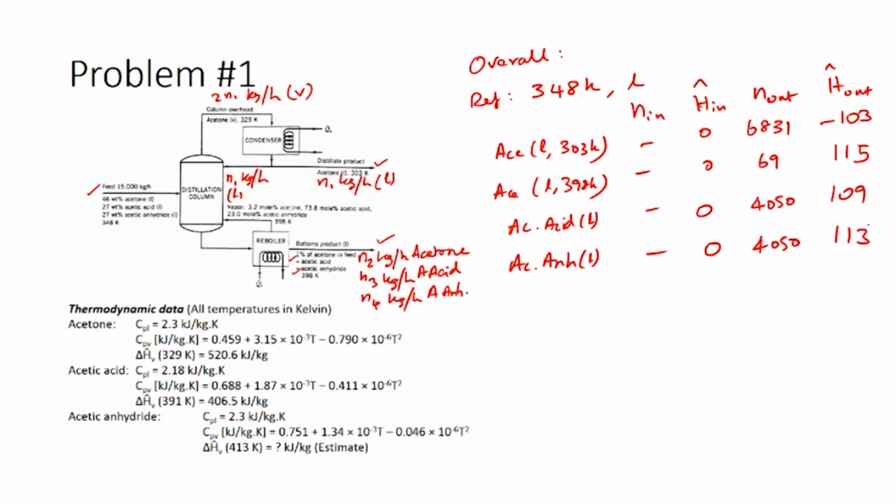So, now we can calculate the total change in enthalpy using this, and we would have to plug it into the general energy balance, the overall energy balance equation, to get QR. So, assuming that there is no energy being used in the distillation column, we will only account for QR and QC, because those are the only terms which have been given to us as the terms where heat is being supplied. So, using that assumption, we will calculate Q dot as QC dot plus QR dot, and fitting it back into the general energy balance equation, this would be equal to delta H dot.